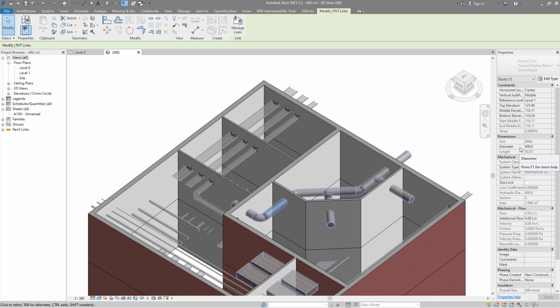But then if you are using a Russian version or German version or some other version of Revit, and your parameter names are different, then actually you need to adjust the Dynamo script, or you can ask me to do that for you, but I am very weak with either Russian or German language. So if you provide me some table in which you will say, okay, for that parameter name in English, you will need to translate that inside your script to be this name, so I can copy paste that, I can do that for you. It's not a problem. But yeah, you should change your Dynamo script accordingly to the Revit version which you are using.